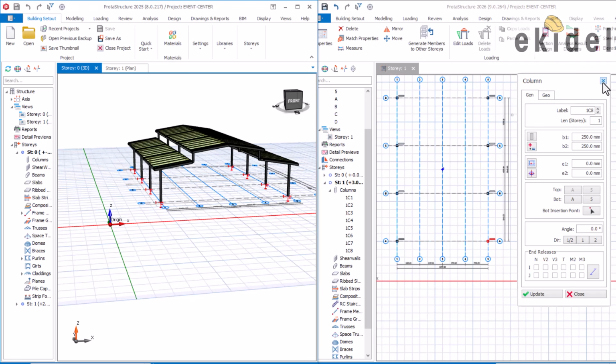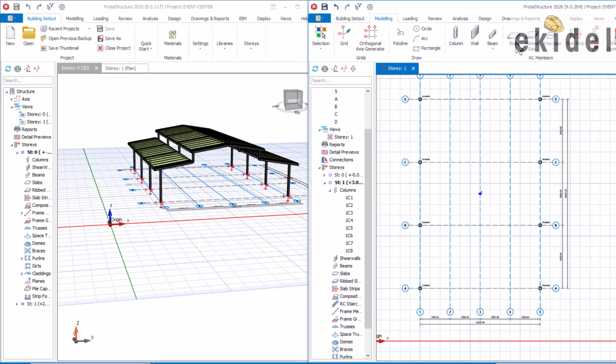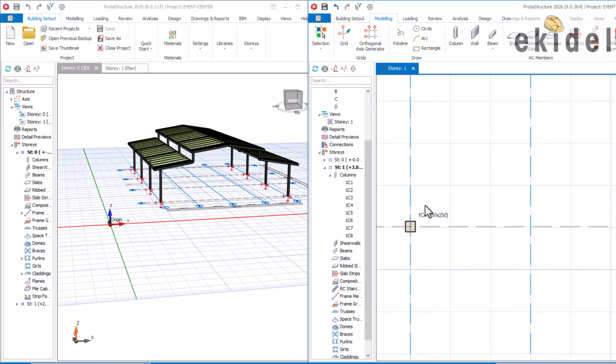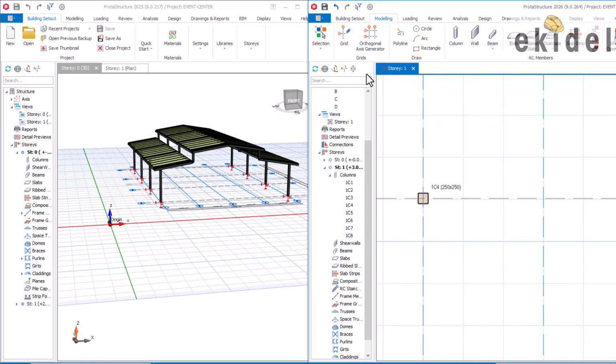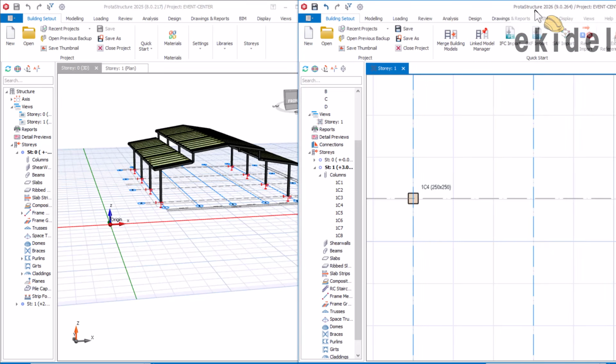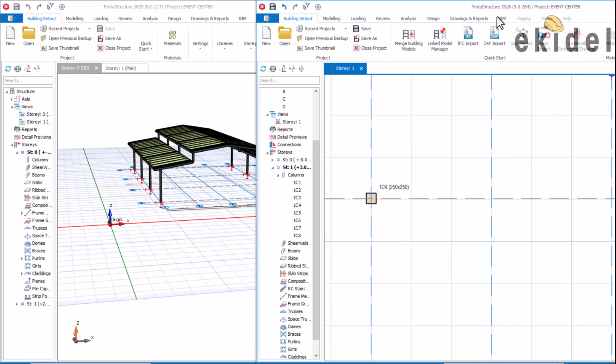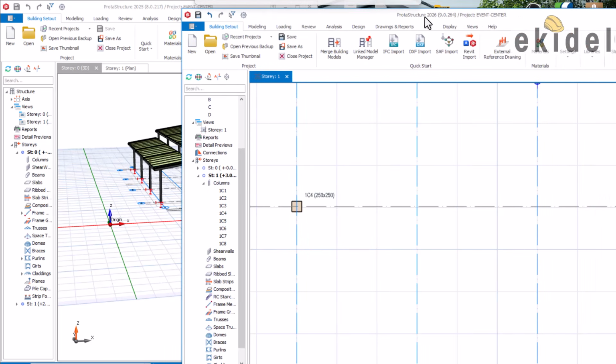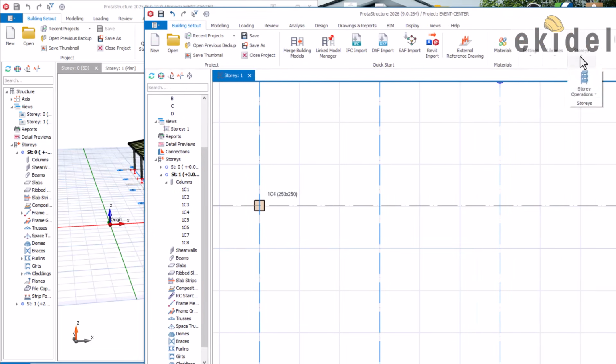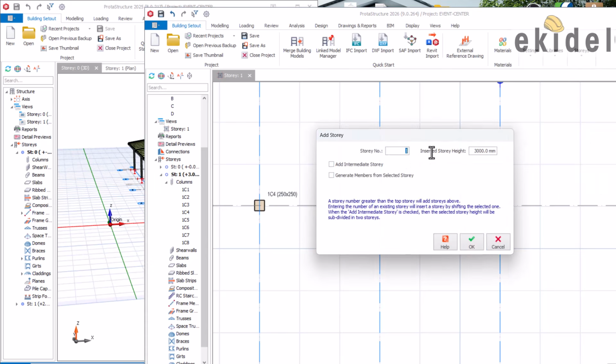But if we click on escape now, then we come and insert story, because we have only one floor here. So this story 1 is going to have only the concrete member. We then come now and build it out here, and then insert our story from here. I will just shift this like this now, and then see my finishing point here, story. Come here and click on here, and then click on insert story, and I'll say insert story 2.